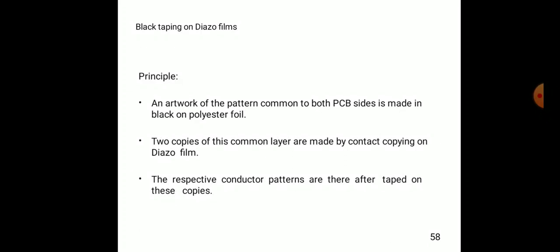Two copies of this common layer are made by contact copying on the Diazo film. The respective conductor patterns are thereafter taped on these copies.